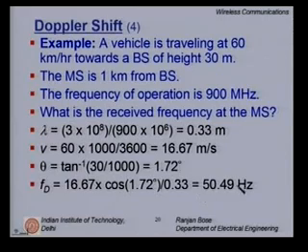Nevertheless, even though this may appear to be a small quantity, this could be plus 50 hertz for multipath ray number 1, minus 45 hertz for multipath ray number 2, plus 30 hertz for multipath ray number 3, and so on and so forth, because the angle is changing. And when you add them up, the distorted signal is very different from what you sent. That's what we have to take care of. So singly it appears innocuous, but it can cause severe problems.